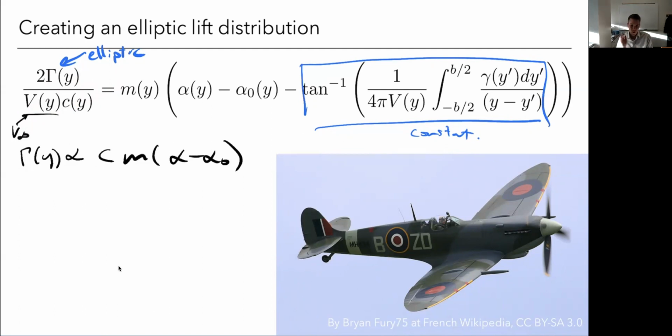If I have the same airfoil everywhere and I twist it all the same, right? So if this airfoil is the same, what things are affected by the airfoil? Well, the airfoil affects my zero lift angle of attack and my slope, right? Because if this is my airfoil that I choose, this is alpha 0, and this is my slope. So when I choose the airfoil, I've fixed these. So if the airfoil is the same everywhere, those are everywhere constant. And if I have an untwisted wing, right, just same twist, angle of attack is going to be everywhere constant on the wing, right? I could pitch the whole thing up or turn and change my angle of attack, but it's everywhere constant.